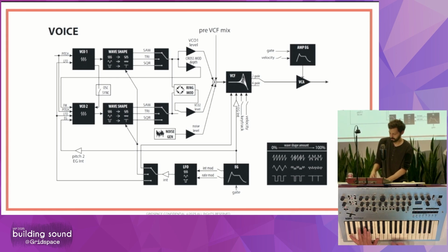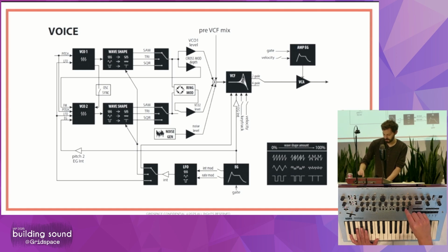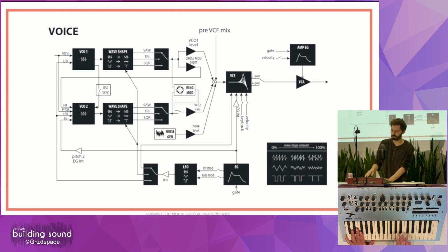So this is just another oscillator, but it is low frequency, as the name suggests. And so rather than hearing it as a pitch, you just hear it as an oscillation of whatever the parameter is. So you can, for example, make it impact the pitch. And that's similar to what we were doing with the envelope generator, but in this case, instead of an envelope affecting it, it's just another oscillator. And so this can actually be a square wave.